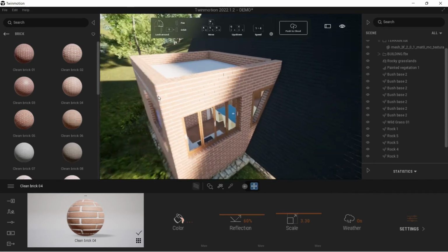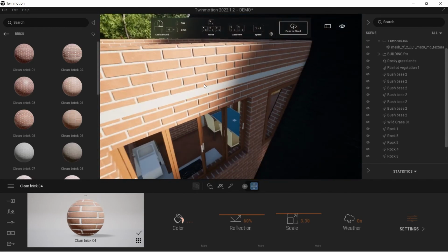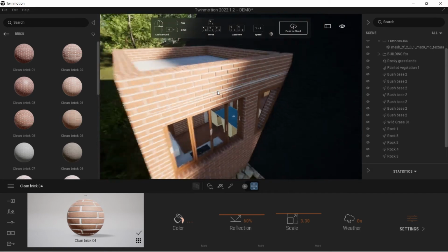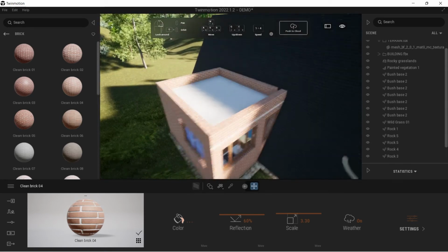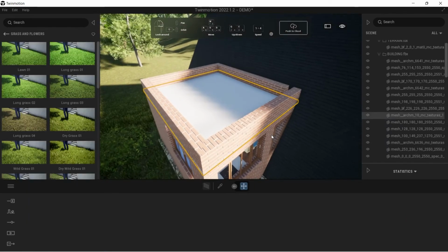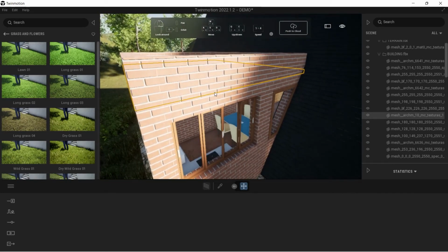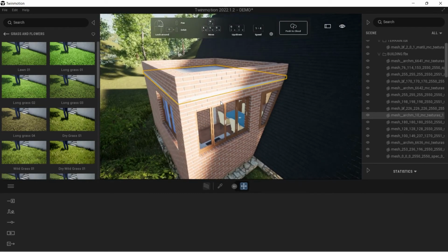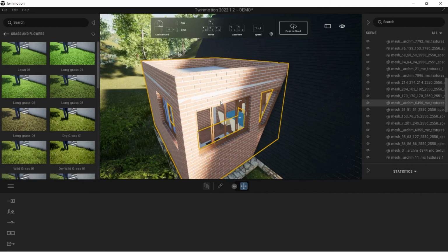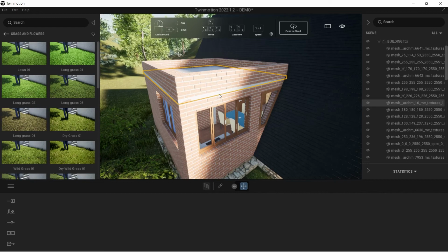These bricks, and as you can see here, we have this flashing element here. It's actually the front face of this slab that is here, because when we created this model, we modeled this slab in a place where two surfaces are coincident. So we have one face of the wall that is coinciding, in the same place, with the front face of this slab. We should correct that in our model. Okay, the good practice would be to correct that in our model, but in this case we have a trick.